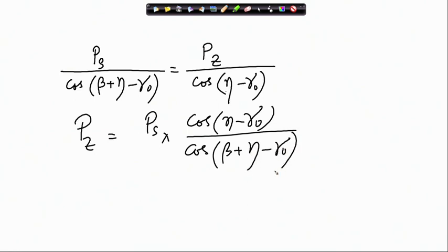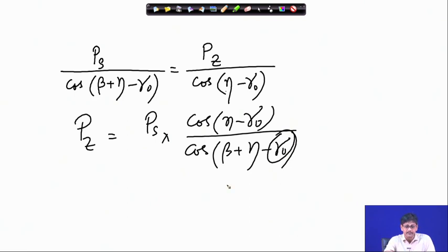So, you might ask me where has all this led us to? It has led us to an estimation of the mean cutting force in terms of the shear forces occurring in the shear plane and some angles. Now, do we know all these angular values? Gamma 0 I know, it is the orthogonal rake. But if someone asks me how do I estimate beta, how do I estimate eta, etc.